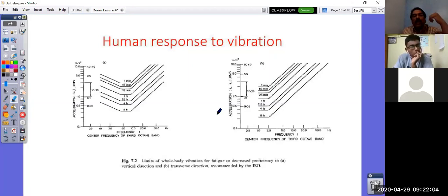Because after all, you are working in an industry later and you are doing your vehicle testing. You are going to calculate your amplitude of acceleration by employing the necessary sensors called seat pad accelerometer sensors. Then you look at the RMS acceleration pursued by human contact, and you do the test for a number of hours, or some test on the test track for about 25 minutes. Then you should get your values so that it will be a safer vehicle. So you will be able to assess.